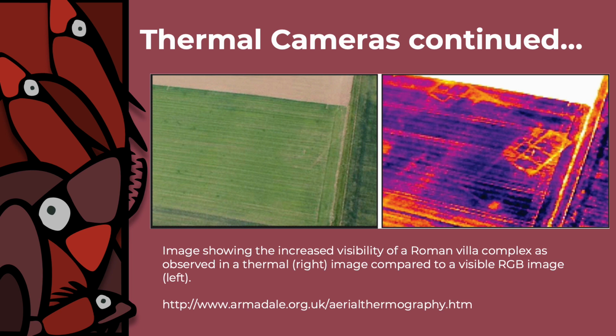Thermal imaging is usually best done at night, as there is usually too much radiation from reflected sunlight during the day, which washes out any of the subtle thermal differences that different features might display. Unfortunately, it is impossible to predict how long after dusk the optimum time to survey is, as it will be different for each site. You might have to try at different times throughout the night to establish the best time.